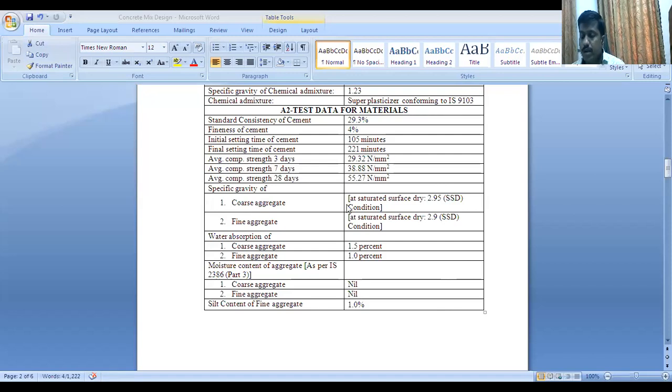Okay. So water absorption should not go beyond 2% at any cost. It may be your fine or your coarse aggregate. 2% पेक्षा जास्त वॉटर अब्सॉर्प्शन नसलंच पाहिजे. Then it is not suitable if it is exceeding 2%.